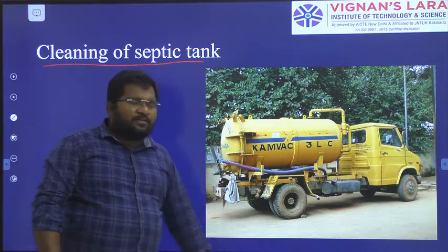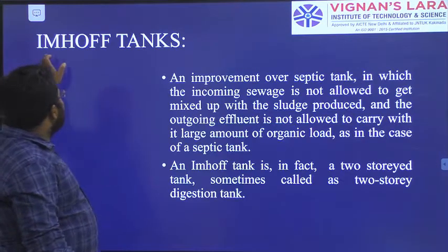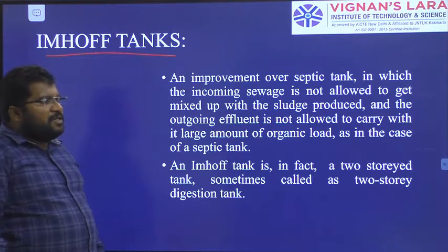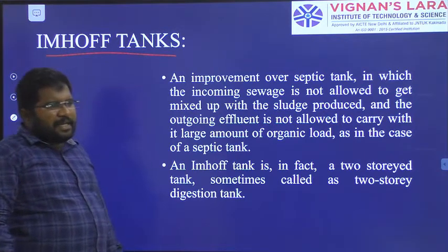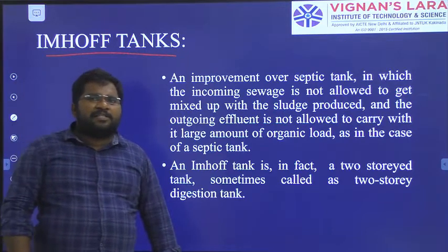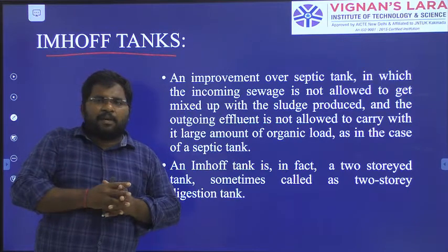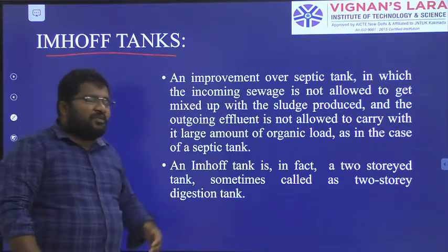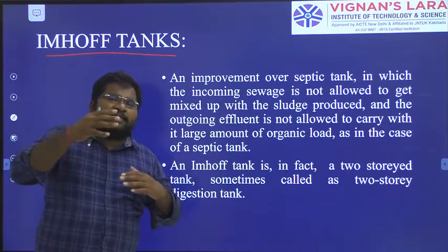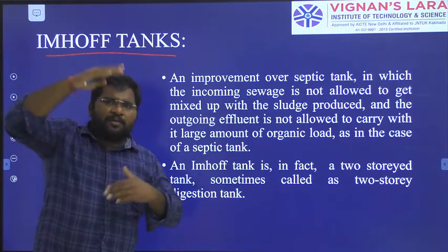Okay, so in that way they are going to clean the septic tanks. Next we have the Imhoff tanks. It is one kind of septic tank, but in the septic tank we saw that both sedimentation and digestion are conducted in a single tank, whereas in the Imhoff tank the sedimentation and digestion are separated into two tanks, up and below.